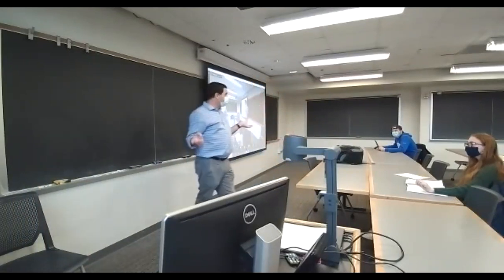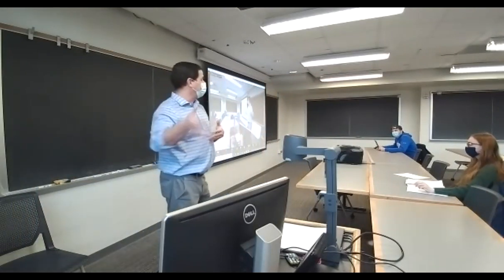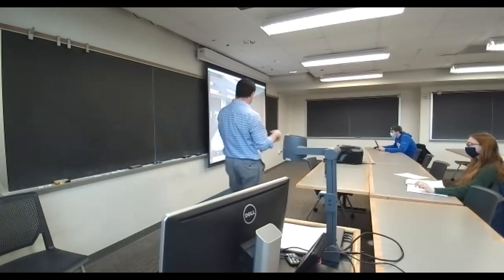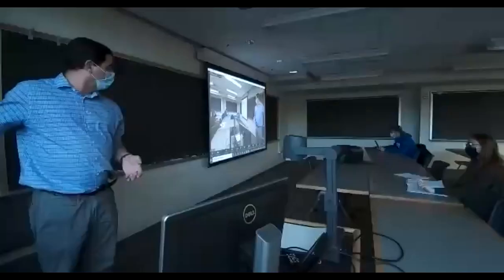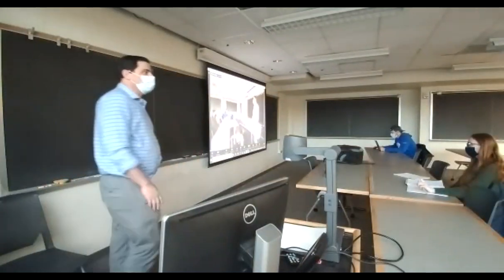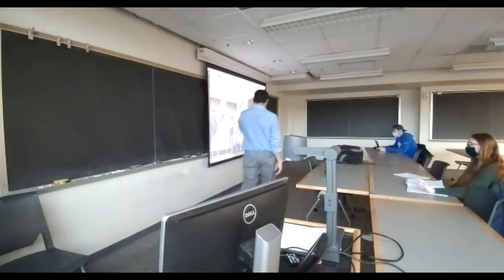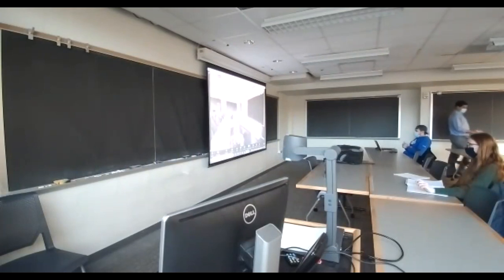The lot size just went a lot higher because the well has to be a set distance. They call them isolation distances away from your sewer field, et cetera, for obvious reasons, right? You're going to work under the assumption that public water and sewer is available, so you can go with the minimum lot